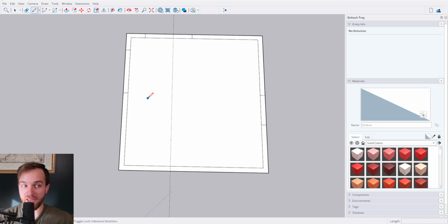We're going to be getting a new vanity for this bathroom, so we'll have some options for depth. However, let's just keep it standard. We'll say it's going to come out 22 inches. So I'll go off that measurement line, 22. And then what I can do is actually just continue from this line and go all the way to the corner. And you have these nice lines for right angles. So I'm on the red axis right now. Click that down, and then we have our vanity kind of mapped in.